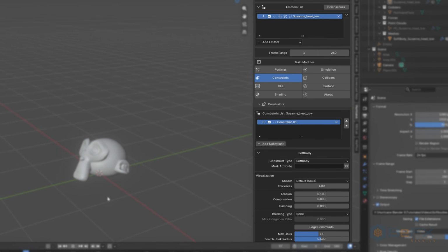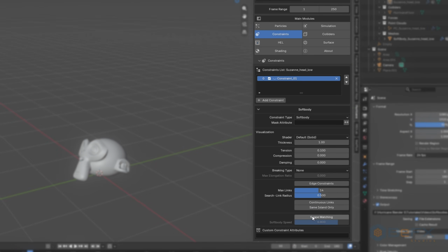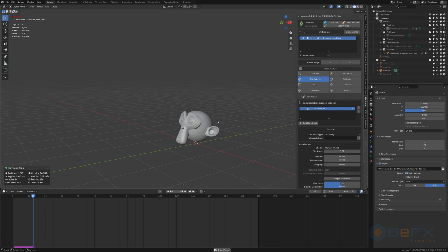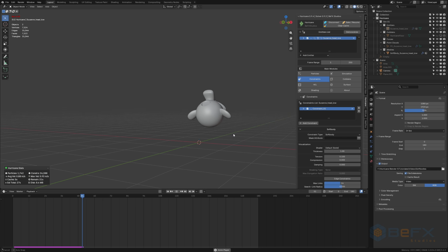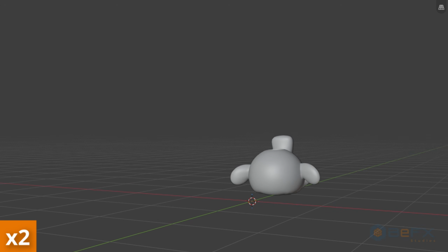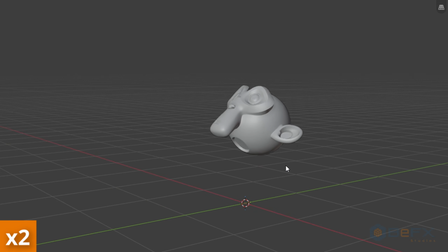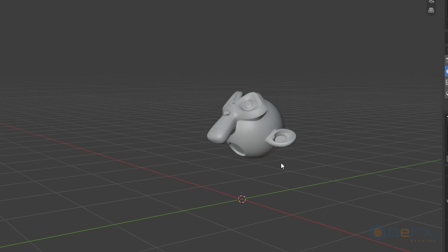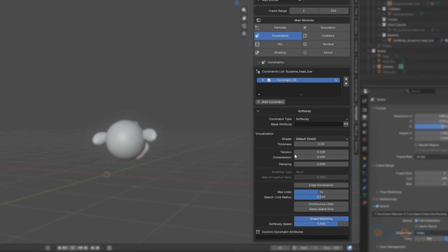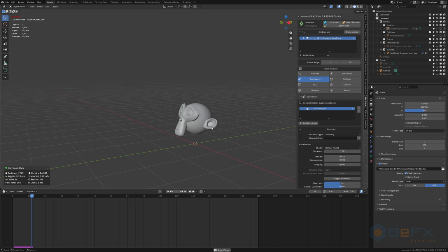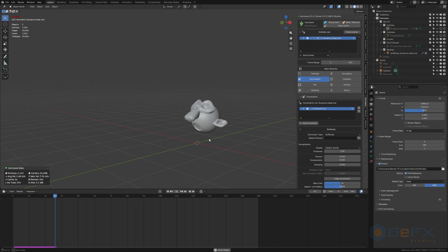If we are aiming for ultra-faithful soft body behavior, deforming upon impact but returning accurately to its original volume and geometry, we enable shape matching. Although these calculations add a slight computation overhead, it guarantees an impeccable result. Enabling shape matching alters constraint sensitivity, requiring more contrasting or extreme values to tune elastically. To demonstrate this, we fix tension at 0.1 and compression at 0, toggling shape matching on and off to observe the stark contrast in mesh response.